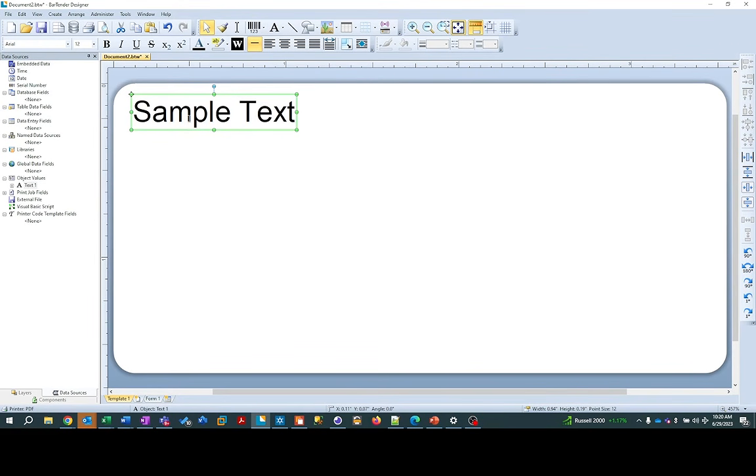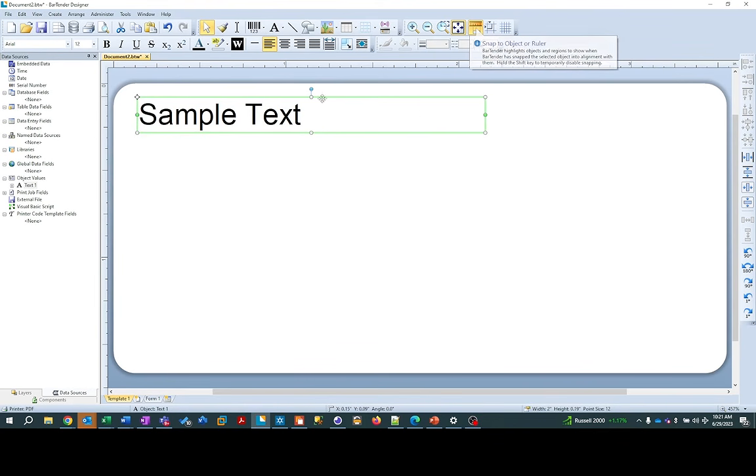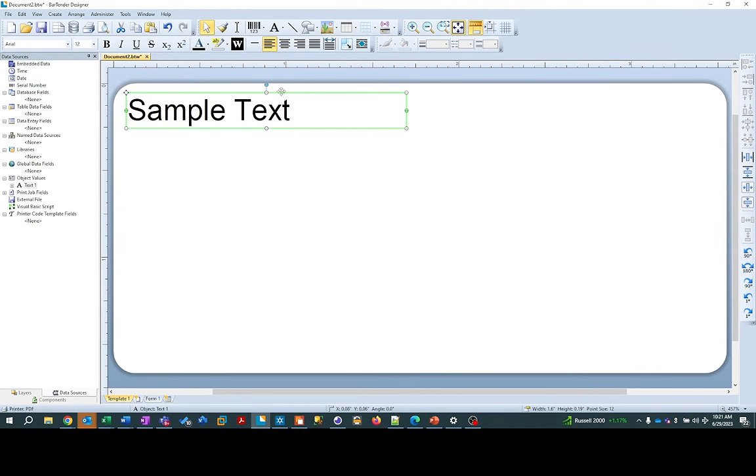So normal is lettering that you're able to use, but once you have to stretch it or work with it, it's not the most manageable depending on your specificity. So we're not going to use normal today, but we are going to go with normal wrapped. Normal wrapped allows us to go in and tweak the lettering as need be. We can delete it if need be. We can tweak the box and there's not any movement to the lettering itself, so it gives us a lot more granular control for our purposes. So we're going to start with the company that we are. We'll go with here.